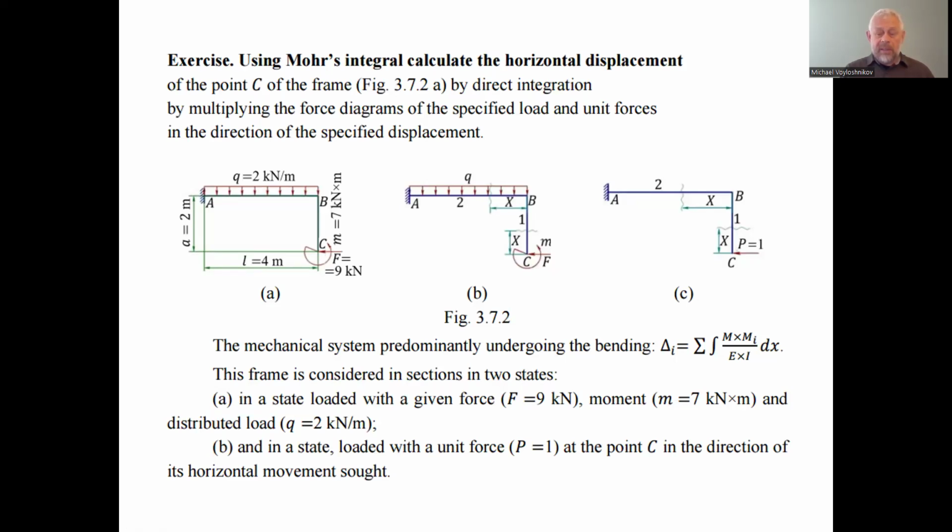Each diagram characterizes the external load and the unit load in the direction in which we have to find the displacement. All these diagrams we have first to find as mathematical equations, and after that we have to substitute this into the integral and find the magnitude of the integral, that is the displacement of the point C under the action in the sought direction and the action of the forces loading this frame.